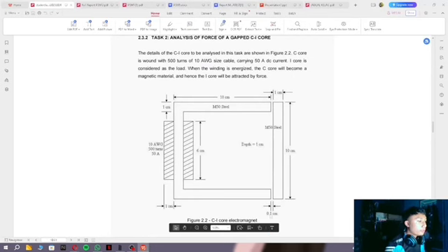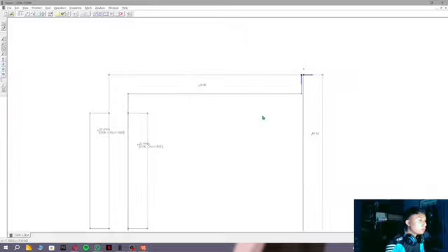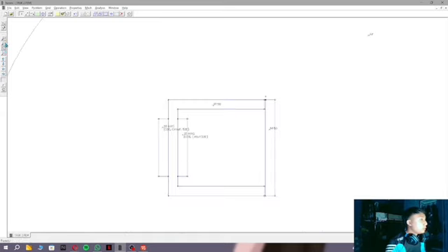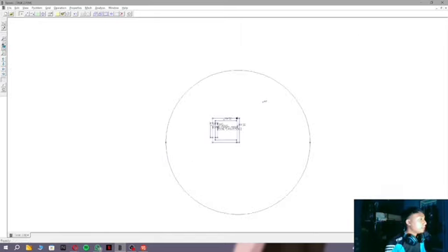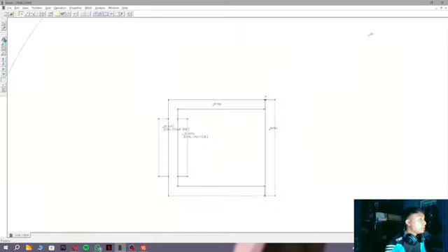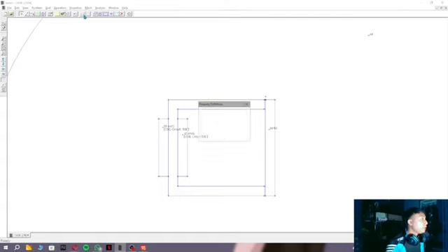It is 0.1 cm. If we take a look at this, all this put inside is air. As we can see at the top right corner, there's air in the circle. That means the surrounding is full of air, and for the C-I core we put in the properties material, which is M15.